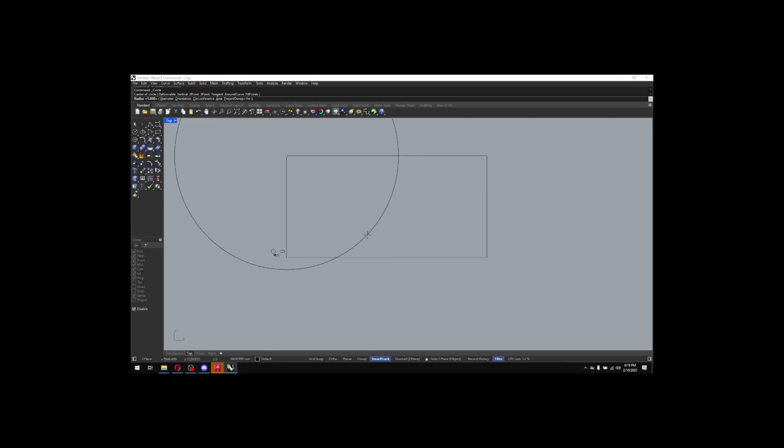Once you get into a good habit, I almost just leave my finger on the Alt button, and I know when I need to turn it on and off. I find that to be a lot handier than constantly having to turn snaps on and off or click certain ones on and off. So again, if I wanted to snap to the midpoint, instead of keeping everything on, I'll hold down Alt, click there, and snap to the midpoint. You'll have your preferences for ones you want to keep on and off. Since I use the Alt method, I usually keep most of these checked, but that'll be your preference.